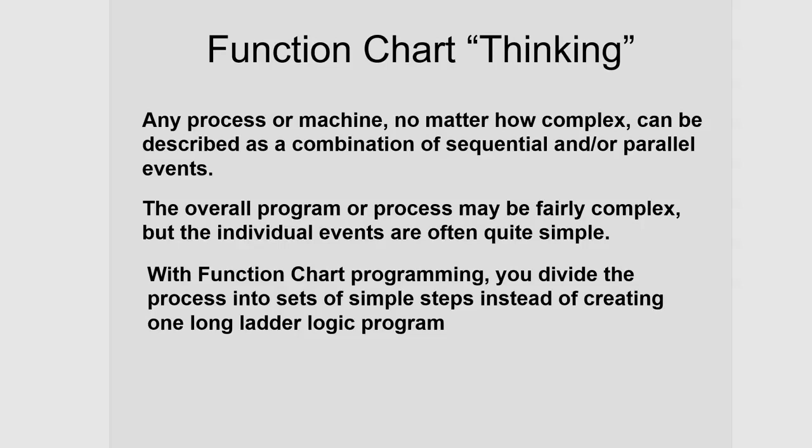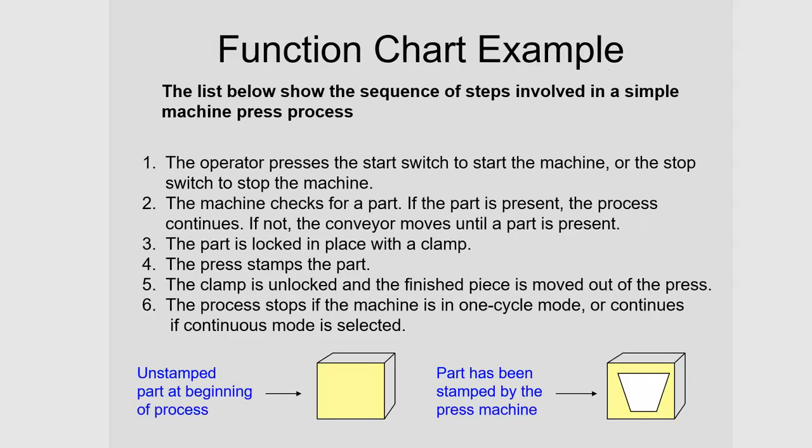The overall program or process can be complex, but the individual events are often quite simple. And that's true with any kind of complicated device. With function chart programming, you divide the process into sets of simple steps instead of creating one long ladder logic program. And that's the power in this. And again, when I show you the next slide, we'll talk about what I mean by that. So here's a function chart example.